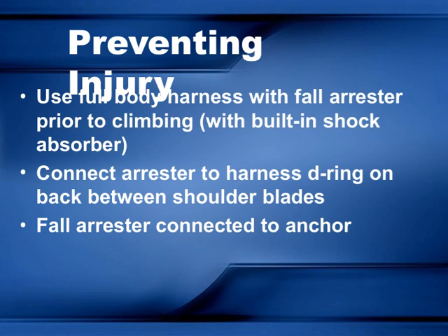Additionally, the fall arrestor should always be connected to a secure anchor point before you start climbing. This connection is what will arrest your fall if it happens, preventing you from falling further and minimizing injury. Overall, these steps, using the proper harness, connecting the arrestor correctly, and ensuring it's anchored securely, are all about preventing injuries and keeping you safe while working at height. Remember, safety always comes first.